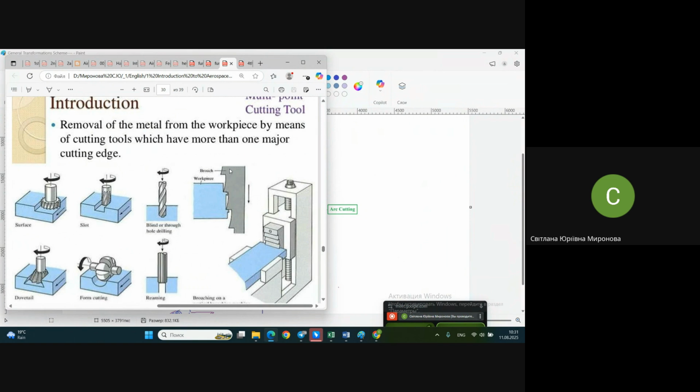And in cross section, what do we see? We see a tool which has some teeth, some blades, and each blade protrudes a little bit farther toward the workpiece, far, farther, and farther each of them. But really this difference between them is some microns. And you have some dozens of these blades along the way.